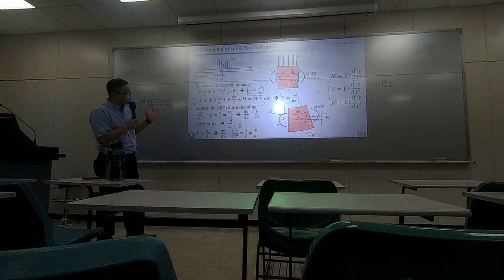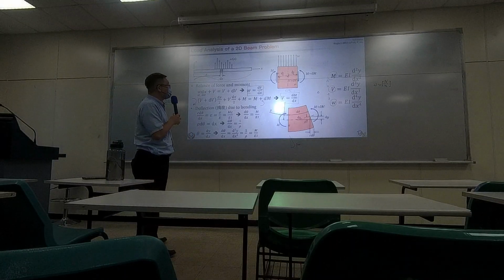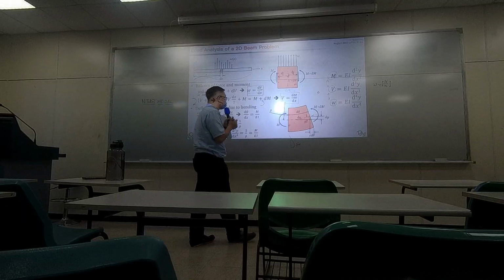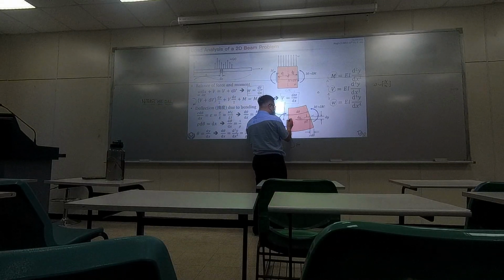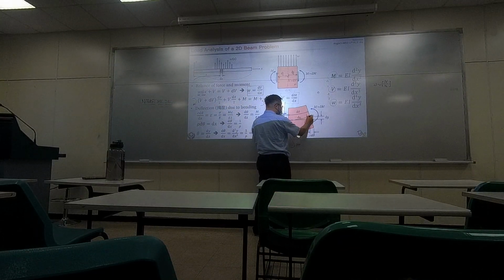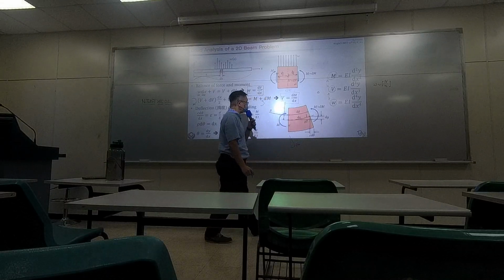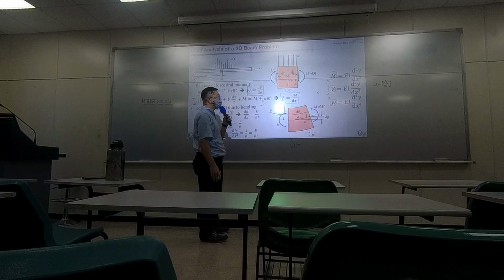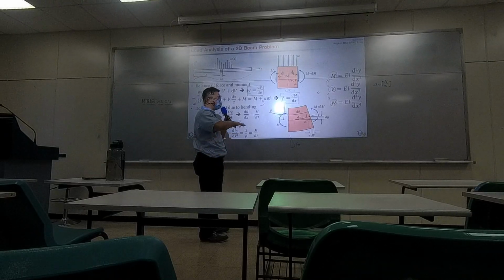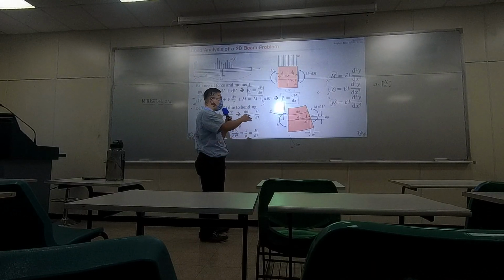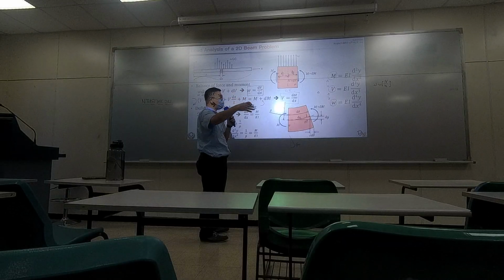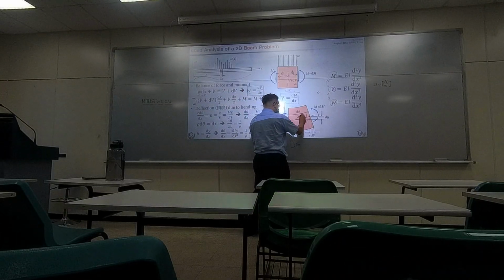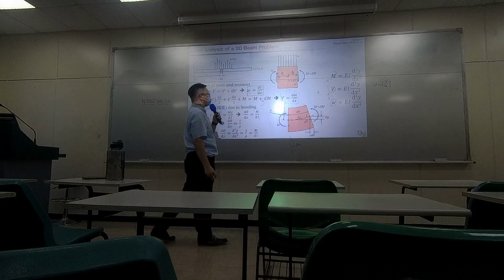Being deformed in such a way. Now, over here, this is the neutral plane. So this arc length, there's no load on the neutral plane. So the length on the neutral plane remains the same. So this one remains dx. Okay?